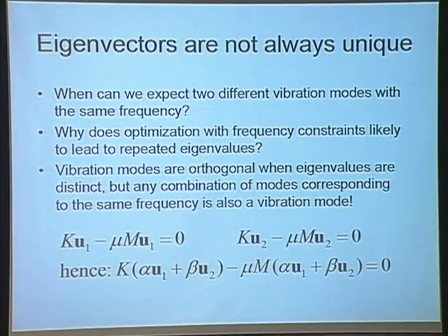That is, imagine that somebody discovered that there is a problem at 55 miles per hour, where something in the car rattles. Let's say it's your bumper. And they start doing things to the car, and the problem goes away, but I'm saying that in the process, it increases the chance that there will be two vibration modes with the same frequency.